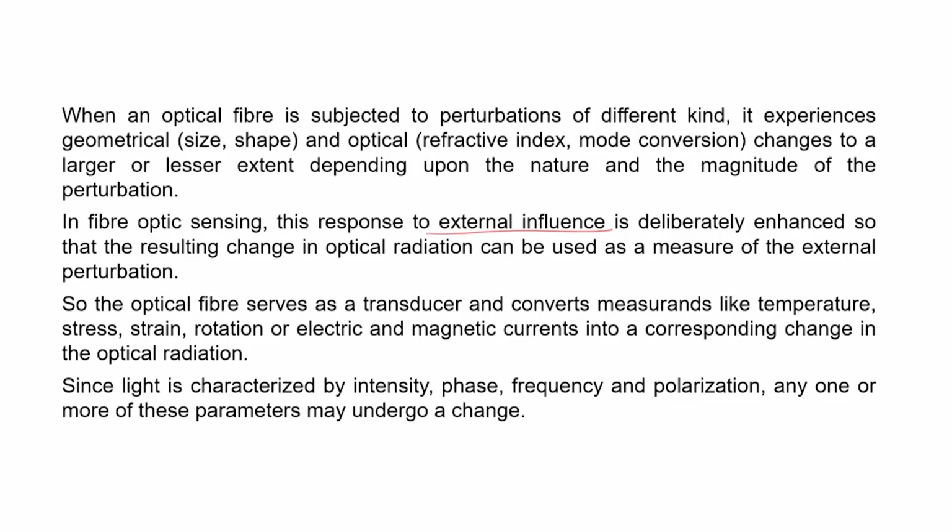In this case, you can have an auxiliary system that can create a disturbance, and by measuring the changes in the optical fiber, you can try to measure the changes that the interrogation is creating. That way, optical fibers can be used for temperature, stress, strain, rotation, electric and magnetic currents, many such things, wherever you can change the environment.